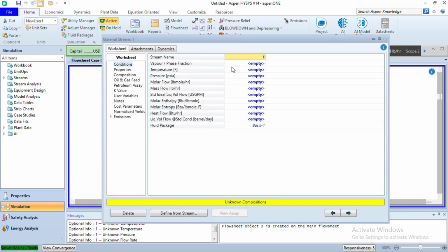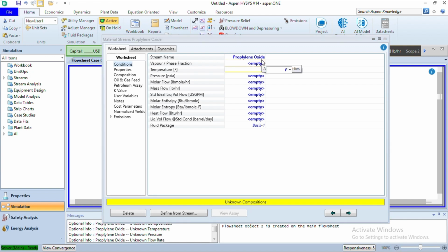Now click on the second stream. Name is propylene oxide. Temperature is 75 degrees Fahrenheit.